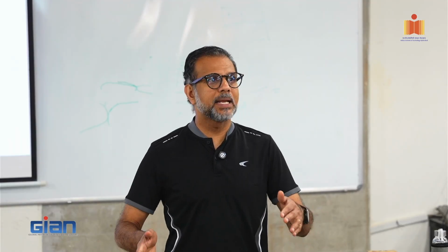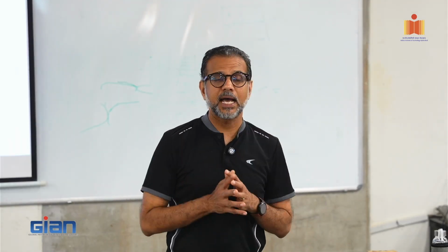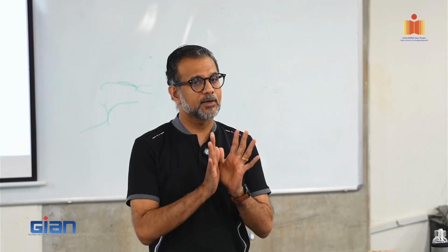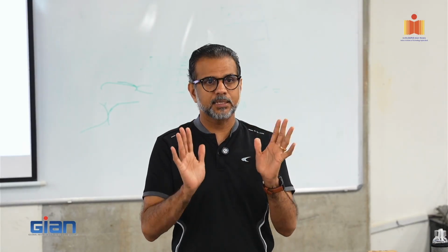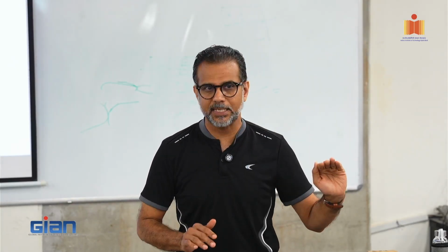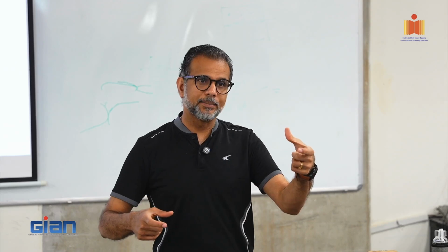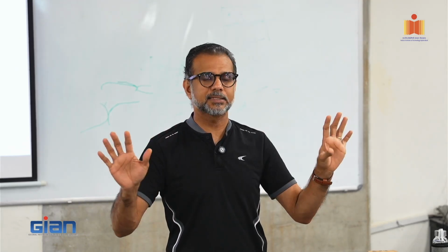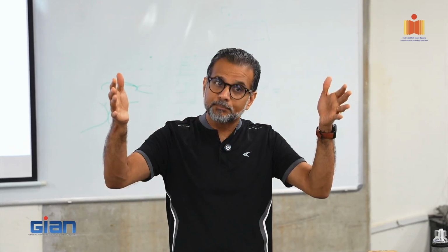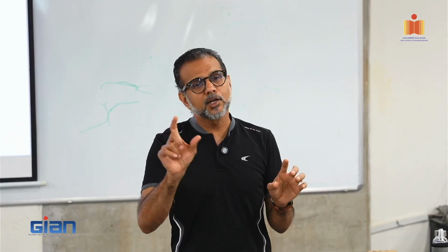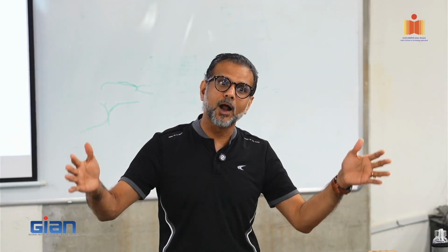For example, if you build a full wall, now they have standards. ISO, the International Standardization Organization, has come out with how to test a full wall. For example, if you want to say my wall strength is so much, how do you test it? That has been standardized: the size of the wall that you have to test, how many meters, what length, what dimension of the filament should be there in that test. But that's still a bulk test. It is still not a material core property. It is still a wall property.